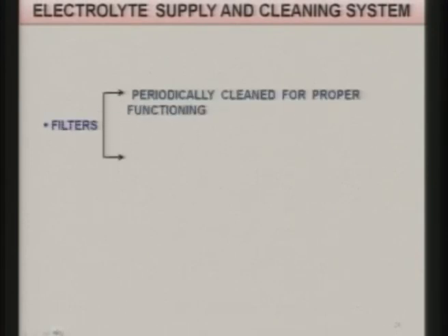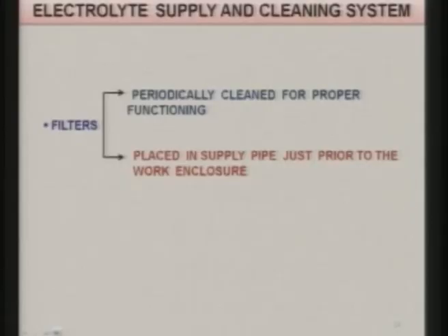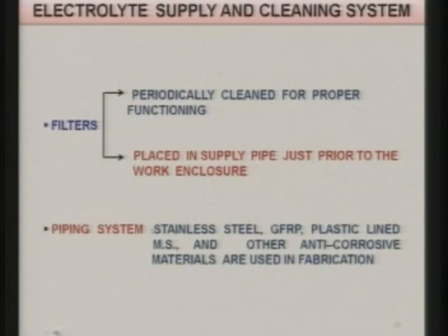Electrolyte supply and cleaning system continues. Filters should be periodically cleaned for proper functioning, and they should be placed in the supply pipe just prior to the work enclosure. There may be more than one filter depending upon the requirement, to make sure that no solid particle goes along with the electrolyte in the supply port.